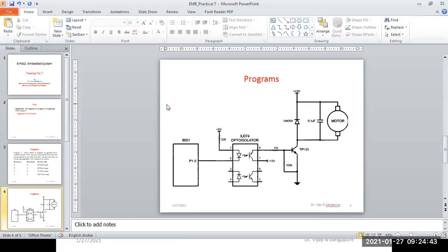Then, if the switch positions are 0 0, this motor will rotate with 25% duty cycle PWM waveform. Means for 25% of time the motor will rotate, and for the remaining 75% it will not rotate. Okay, so that is not the case. Because power is being controlled, the motor will continuously rotate but with speed of 25%. So I will take my words back. This motor will rotate with 25% speed when the switch positions are 0 0.